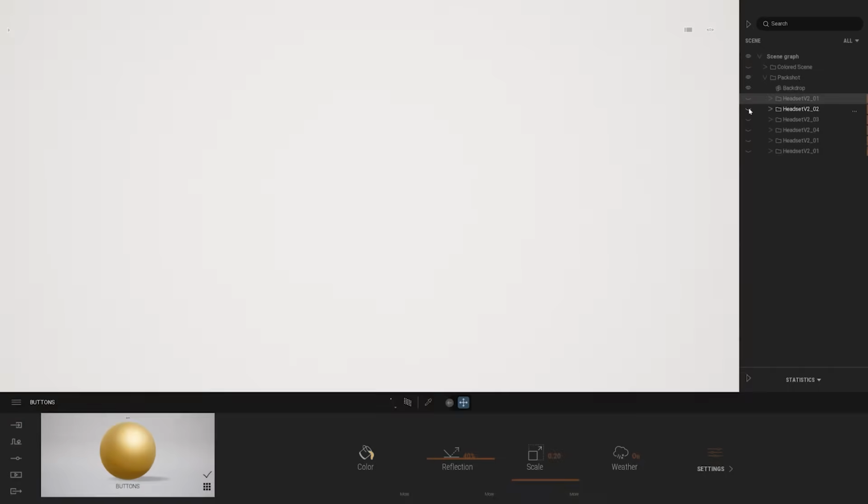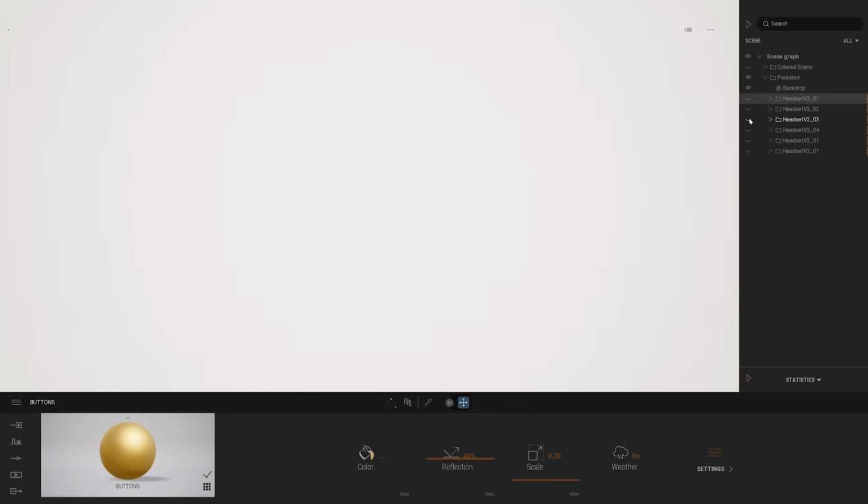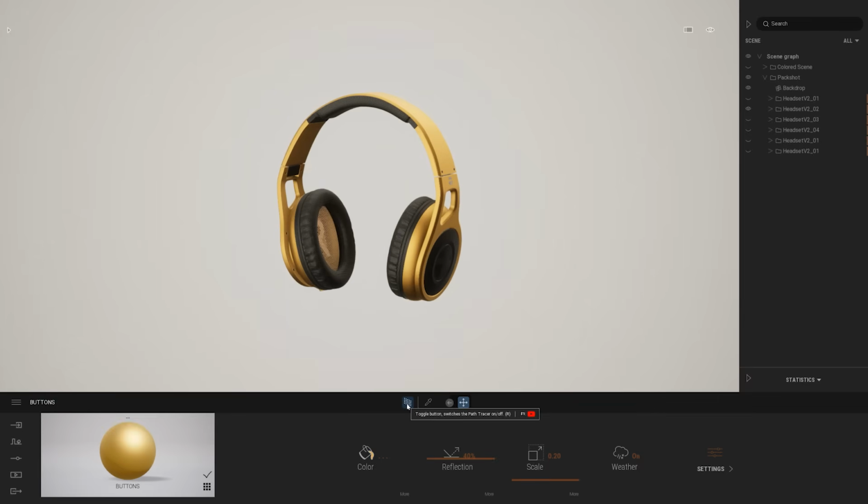Throughout this webinar, I'm going to use the Path Tracer. The Path Tracer is a DXR accelerated physically accurate rendering mode that allows you to basically create final pixel imagery. You can turn on the Path Tracer with that simple icon in the toolbar. And if you want to learn more about the Path Tracer, we have a dedicated article on our support website that will let you know all the details and the system requirements to run it.